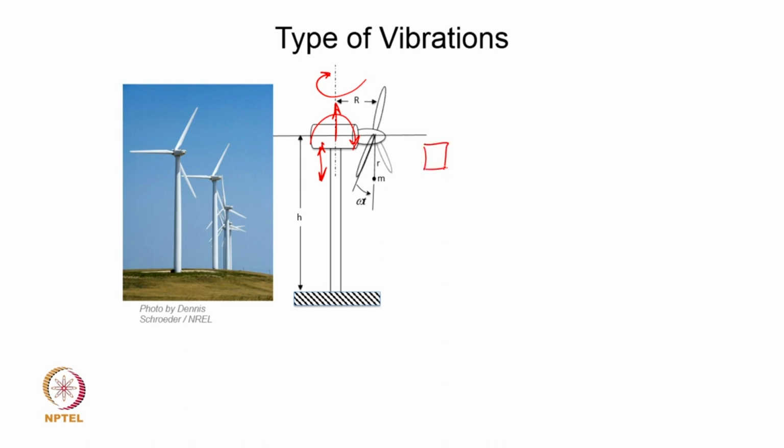So, as we discussed, there would be a mass of the nacelle which is quite heavy compared to the mass of the column, and then we can have the simplified vibratory model like this with the mass of the nacelle here and the stiffness of the column defined by the spring. And we all know that the stiffness of a circular bar like this is given by AE over L from our basic solid mechanics: cross sectional area times the modulus of elasticity over L becomes the longitudinal stiffness of the column, that gives you the Kc value, if you are interested in knowing how the nacelle vibrates vertically up and down. Okay.